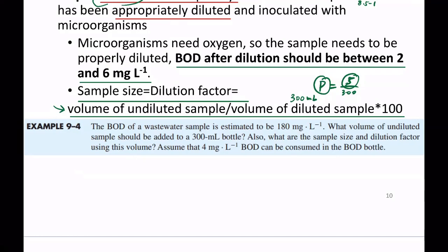The correct answer should be the third answer because we're measuring the diluted sample, all right? So it is diluted twice from the wastewater. So you need to multiply that by 2 to get 10 milligram per liter, right? This is a very important concept. We're going to carry this through the entire semester, okay? So if you don't know the reason why this is 10, let me know or let the TA know, all right? So you also get some homework problems regarding this concept.